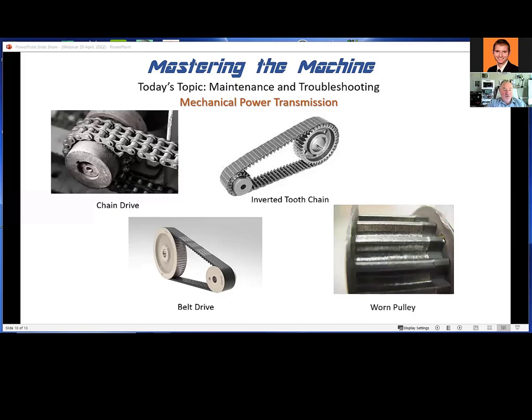But you could monitor these and simply look at pictures, 1 week apart, and you could probably see a wear on a pulley or fraying of a belt or things like that, and not even automate it. I think the video footage itself is worth quite a bit, but of course that takes a human being doing the checks.